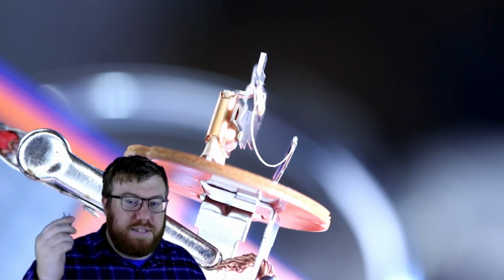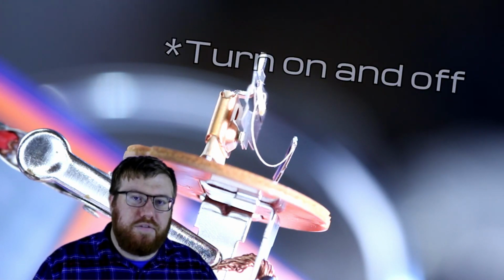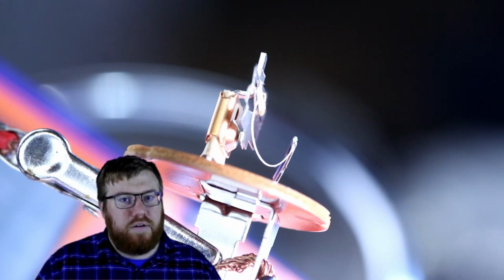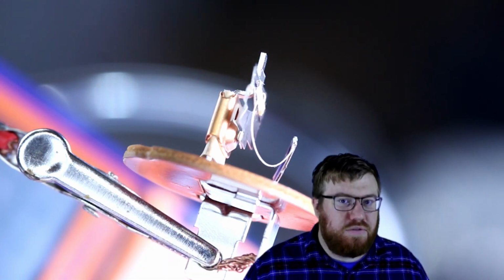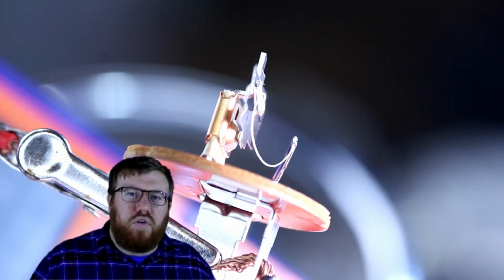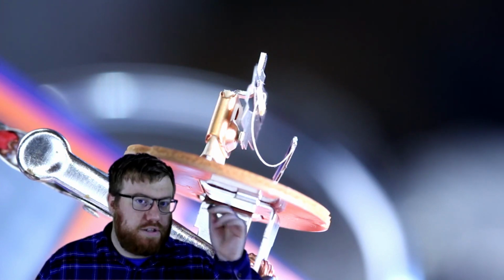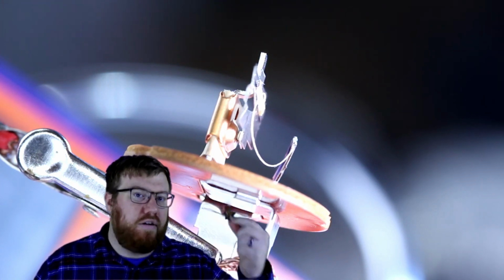Your turn signal bulbs, as in the front one, the rear one, possibly one in the mirror, and any of your marker lamps that turn on when a turn signal is activated, are all in parallel. The more light bulbs you add to the circuit in this way, the more amperage you get overall when the circuit converges. In order for a flasher unit to handle all those bulbs, it has to be at that point where the circuit converges and it's handling all of that amperage.